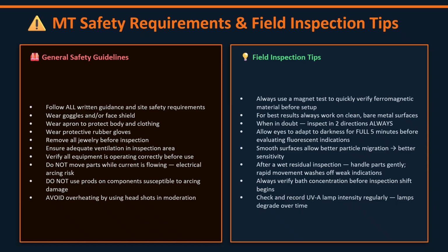Electrical safety deserves special attention. Never move a component while direct inspection current is flowing. Poor contact can create arcing, which can damage the component and injure personnel. Prods should not be used where arc strikes are prohibited. The field tips also protect inspection quality.